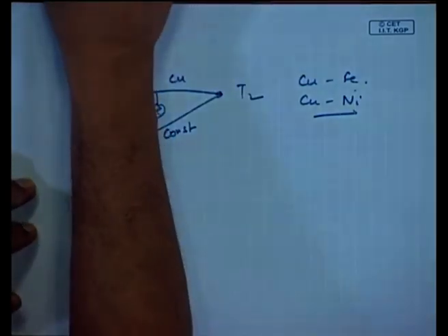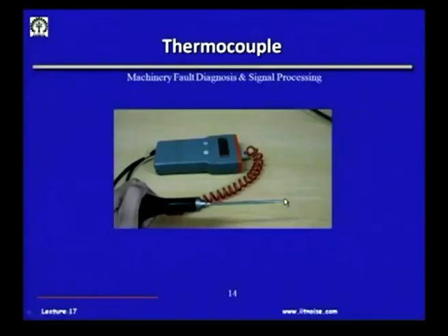So, this is just one end, because you would have studied the thermocouples, which means I need two ends. Where is the other end? The other end could be an ice bath or a boiling point bath, actually all I need is just the reference voltage.